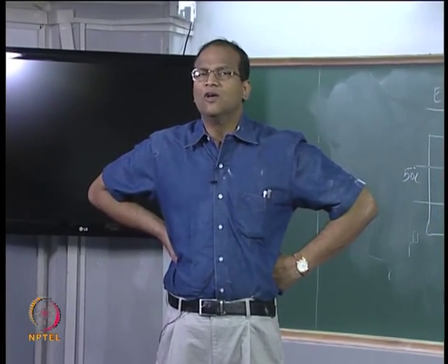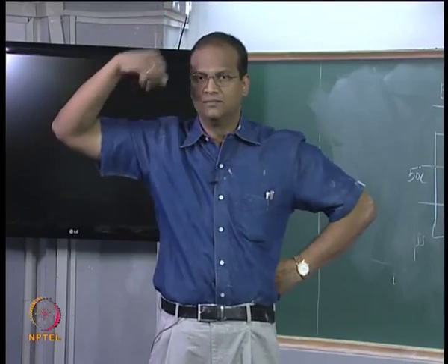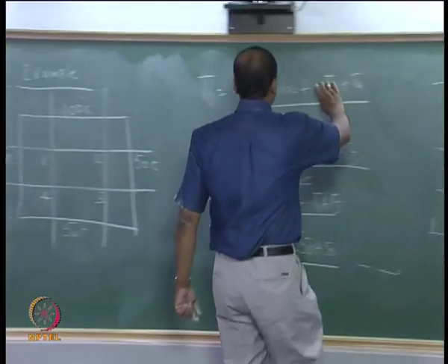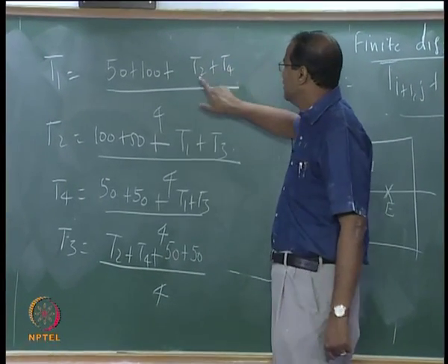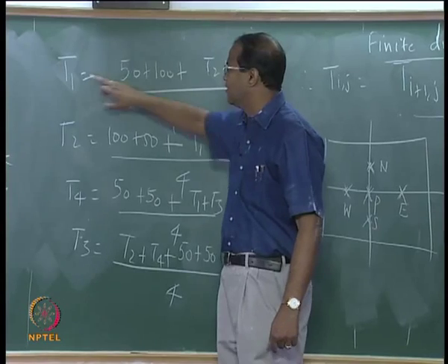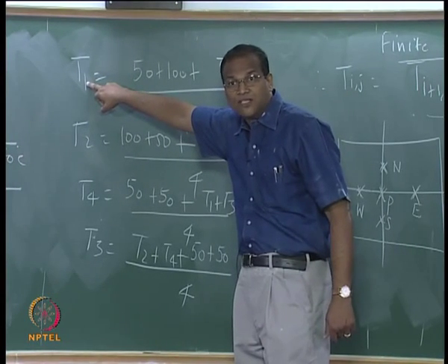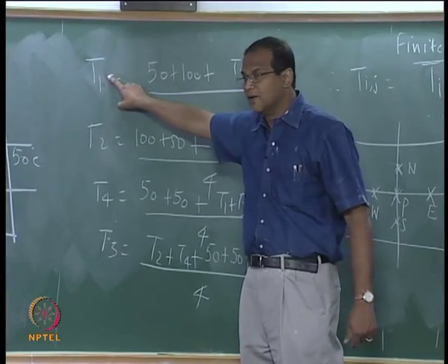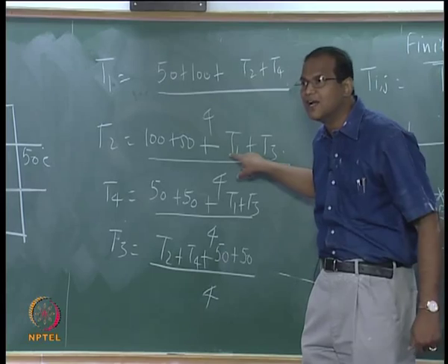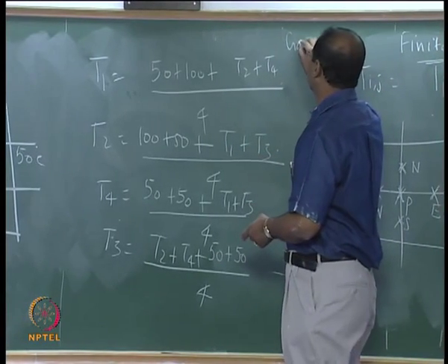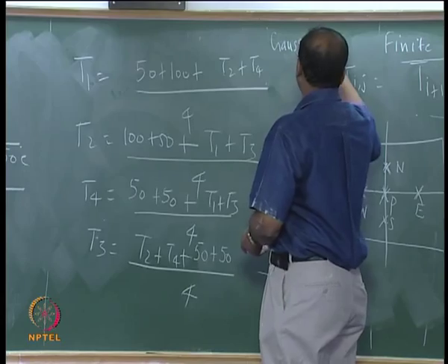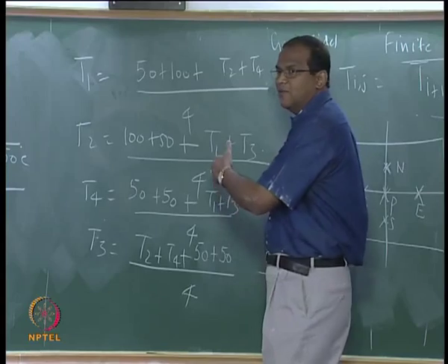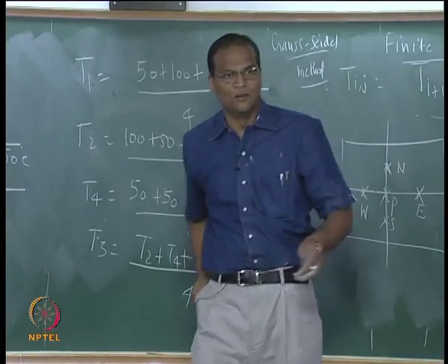Let T1 equal T2 equal T3 equal T4 equal 70 degrees centigrade, first iteration, okay. Once it is 70, I will come to T1 first. 70 plus 70 plus 100 plus 50 by 4, I already have T1. Now watch carefully. Now T2, T3, T4 are 70, but T1 is calculated. So when I go to T2, I use the latest update of T1. If I do that, that is called the Gauss-Seidel method. It has to satisfy diagonal dominance and all that. Fortunately, it automatically satisfies. You don't have to worry about this here.